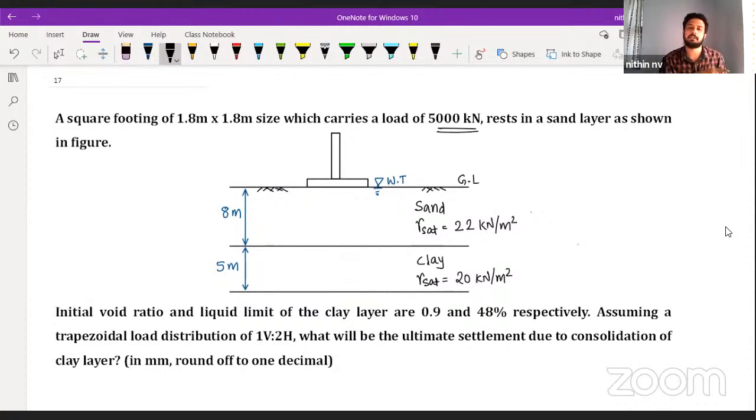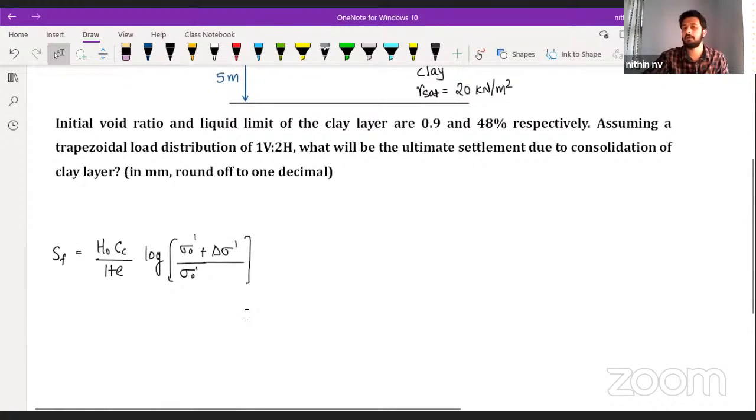In our previous sessions, we have seen the calculation of effective stress, including capillary effects. That is the initial effective stress calculation. Now, because of the application of load, effective stress will increase. If you add that incremental effective stress to the existing one, you are going to get the final one. So can I write it like this also? In some material you will see this equation. Very simple, according to what we have already studied.